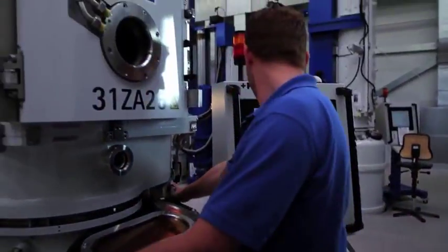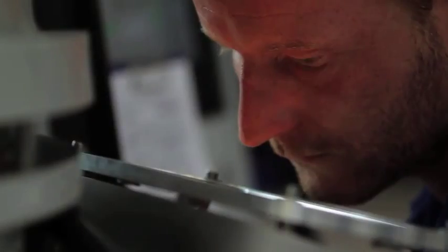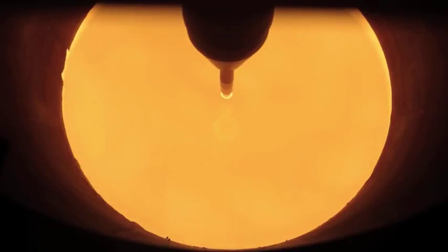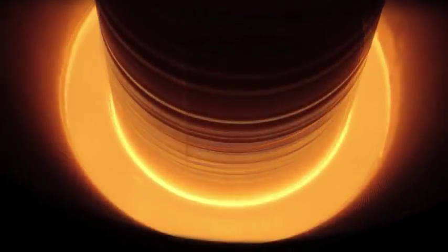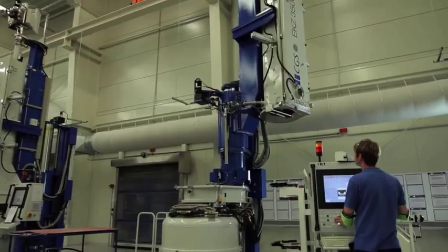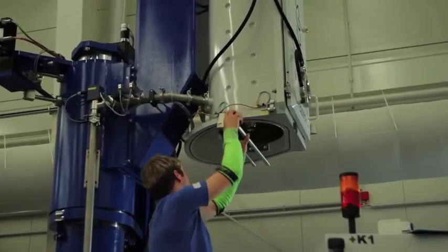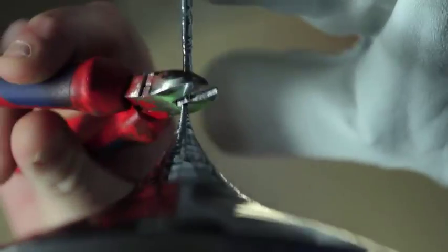To generate solar power, the photovoltaics industry utilizes the semiconducting properties of silicon. In special ovens, raw silicon is melted at temperatures of over 1,400 degrees centigrade. A thin rod, known as the seed crystal, is then submerged into the liquid raw silicon and pulled back up very slowly. At this step in the process, the liquid silicon accumulates on the seed crystal and solidifies. Over 4 days, a silicon rod of up to 2.8 meters length takes shape.